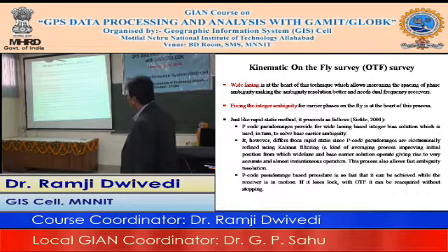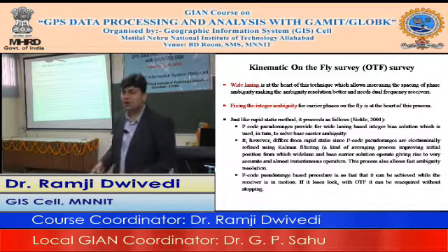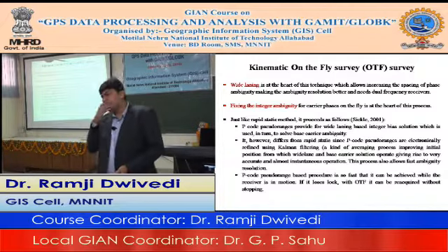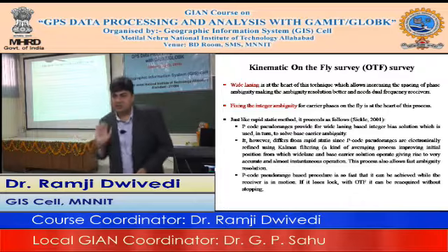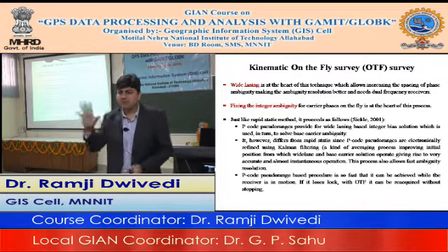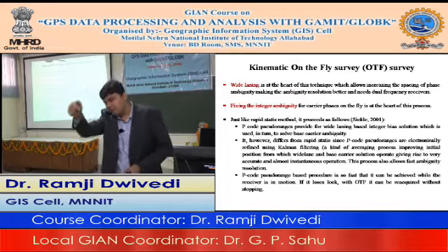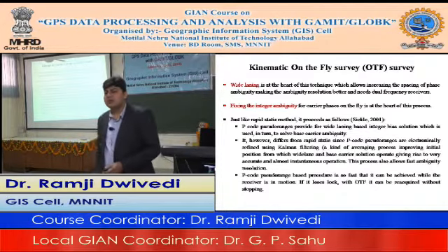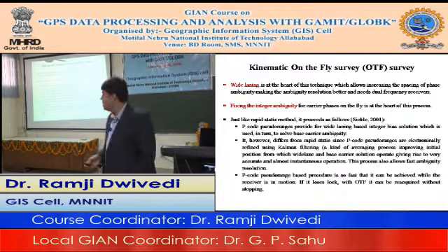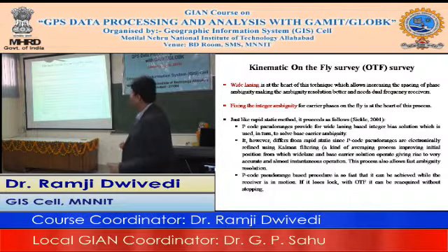So yes, the kinematic OTF survey. Wide lane is at the heart of this OTF. You prepare the lane combination, and some of you have already seen in EDM measurements, where the reflector is there, and from EDM you make certain short and long wavelengths to measure precisely the so-called decimal point of range estimation. So with that understanding also, the lanes are prepared to resolve that ambiguity in a faster sense. So for the carrier phase, on the fly mode is the heart of this process. P-code pseudo range provides the wide lane based integer bias solution.